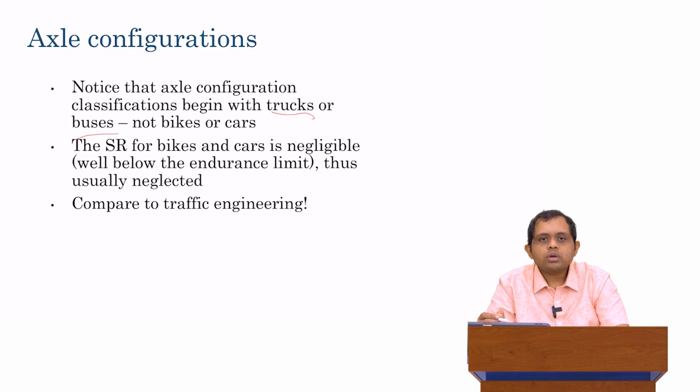If you actually do a mechanistic analysis, and we've actually done this in my research group, so I can say this definitively. If you see what is the axle load of a car or of a bike or of an auto, and you do the mechanistic analysis and you calculate what is the stress ratio which is developed due to these vehicles, it is negligible.